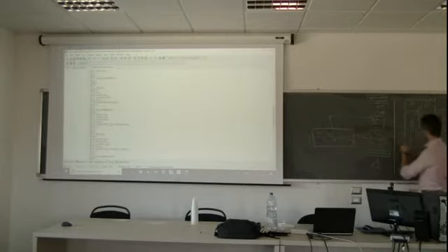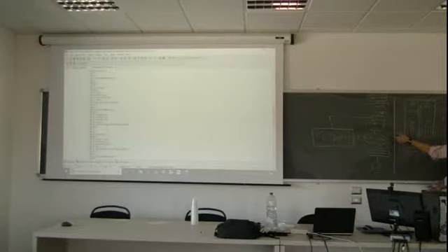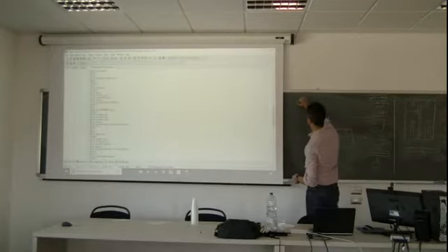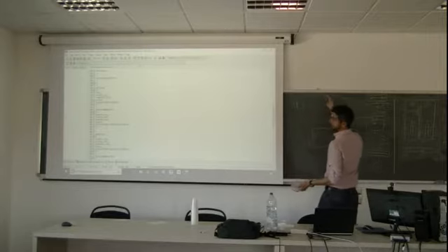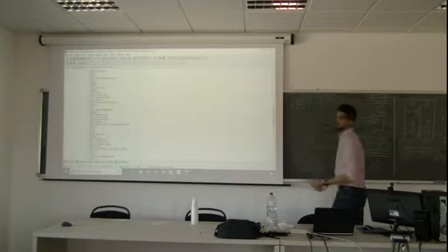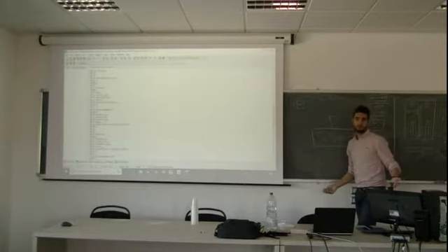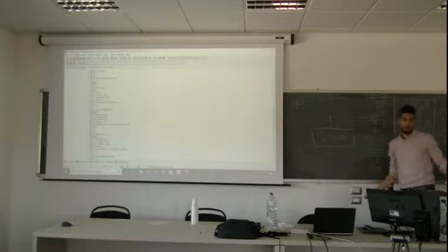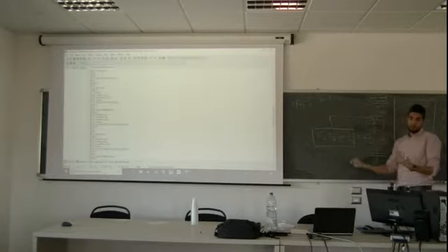How is the first node? The first node is adiabatic on one side and has conduction on the other side. Right? So it's like this. This is node P and this is node east. The question here is Q east and generation. Generation minus QE equal to 0. Correct? We don't have any more physics here. We don't have conduction coming from the west because it's adiabatic.